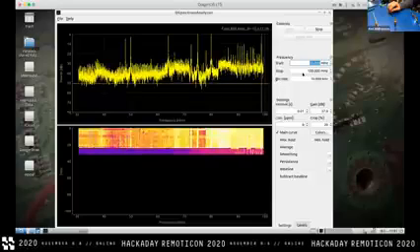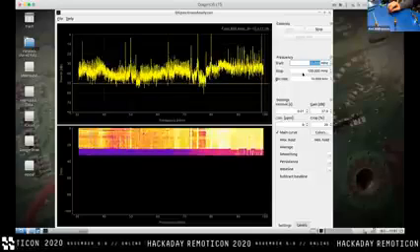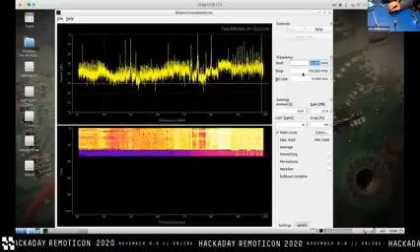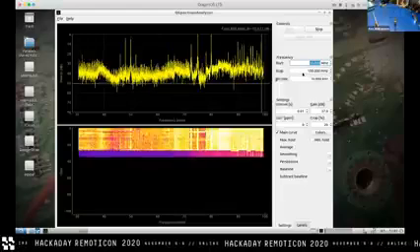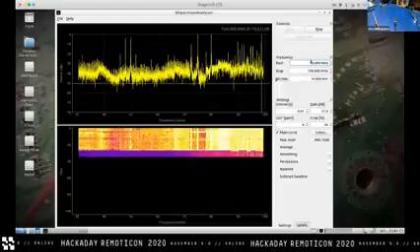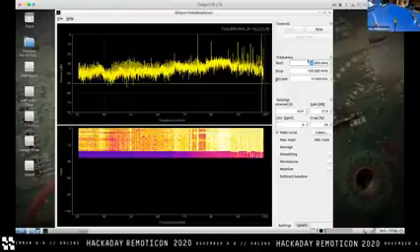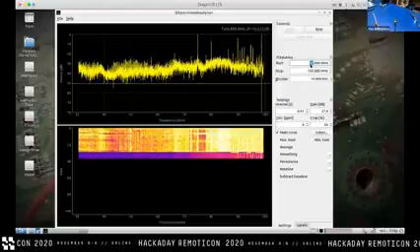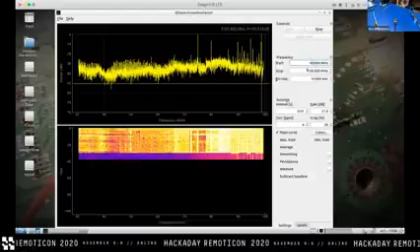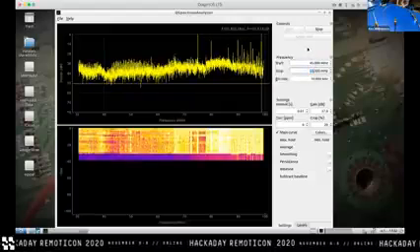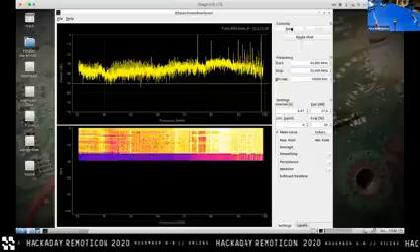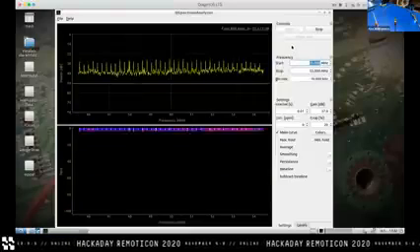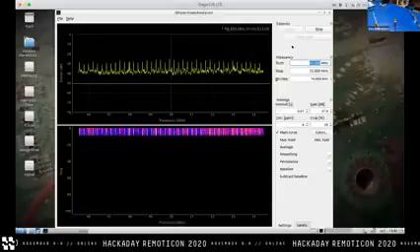But anyway, what we do now is, okay, we see those peaks. We see 48 and 50 megahertz as definitely peaks. So let's narrow our gaze a little bit and search just between 45 and 55 megahertz. Oh, my keyboard is again not working. 45 and 55 megahertz. That's still more than the real-time bandwidth of our SDR, so it's not going to happen instantly. But, oh boy, that certainly happens a whole lot faster.